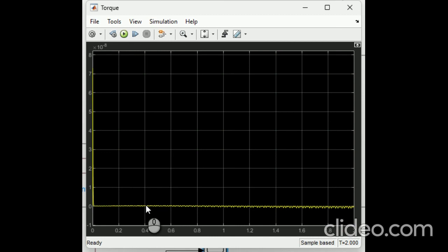Ideally, you would want to specify a joint trajectory that is not jerky. So for example, it would start off smooth, reach a peak velocity, and return to rest very smoothly. And those are things you could experiment with later on.